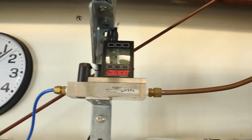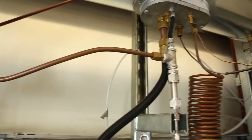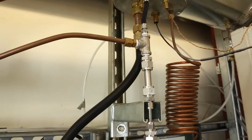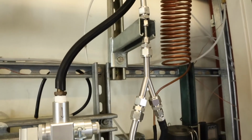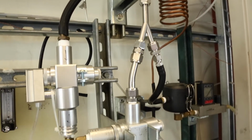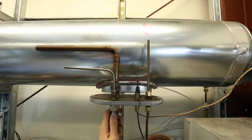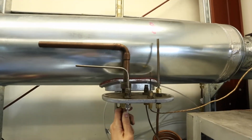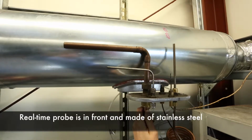To reduce the concentration of emissions for the real-time instruments, we incorporate a secondary dilution system. As with the gravimetric system, we use an isokinetic sampling probe to sample emissions from the dilution tunnel. However, this sampling probe draws only about 1 liter per minute compared with the gravimetric system's 16.7 liters per minute. So, to maintain an isokinetic flow rate, the real-time sampling probe is smaller in diameter.